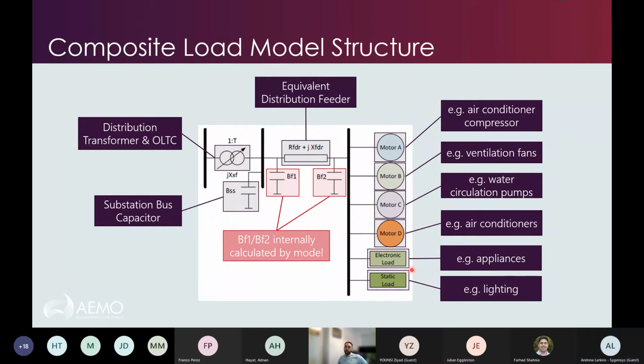But we know that based on studies conducted, extensive studies conducted especially in the US, that the first part of a VSD, mind you, we're talking about an aggregate model, the first part of a VSD during a voltage disturbance event is accurately captured, but as that voltage recovers, the current would be limited to 1.2 times as it returns. So that's like the average that these studies have shown. So the current gets limited to 1.2 times on the return path of that end of that voltage disturbance, following the fault. So that's not actually captured. And we see that in our validation studies, that we're not actually capturing the complete dynamic response of a VSD in that electronic load model, because it doesn't represent that post-fault effect that VSDs have.